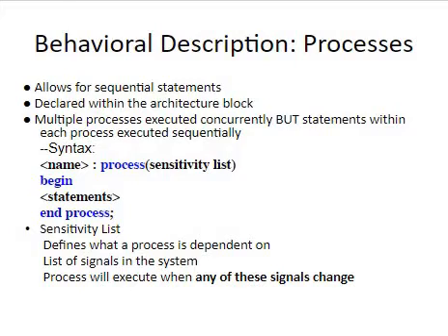What does this mean? Now imagine you have two or three modules of sequential circuits. If you want to write three processes inside the architecture, one process will be dedicated to one part, the second process to the second part, and the third process to the third part. The compiler will start executing all three processes at a time, but the steps inside each will be executed one by one. Do you understand my point? So every process has a sequential flow of execution inside it, but every architecture has a concurrent flow of execution inside it. Remember this, please.